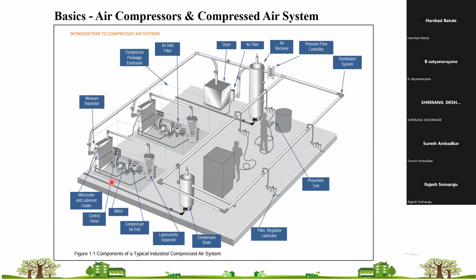Your power consumption is then on the higher side. So the optimum placement is also important in the compressor section. FAD has a correction factor, and during your normal assessment in an energy audit, you can apply those correction factors.